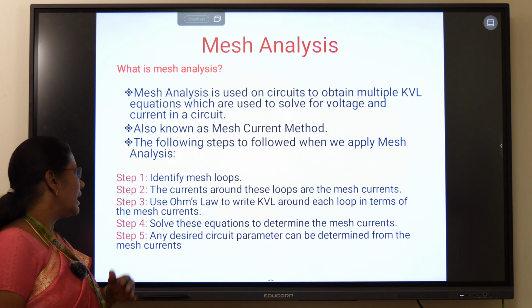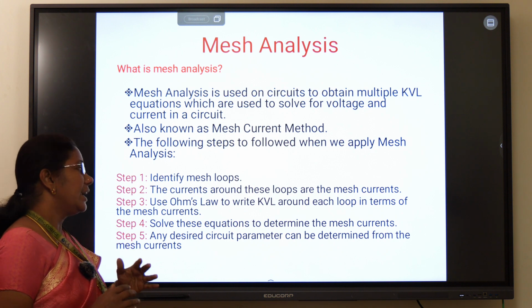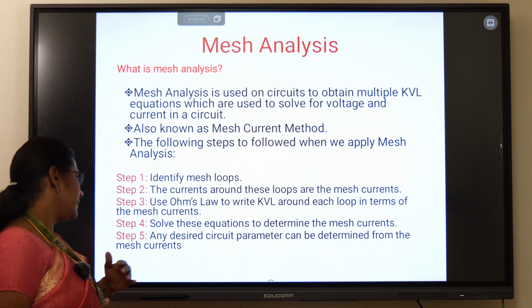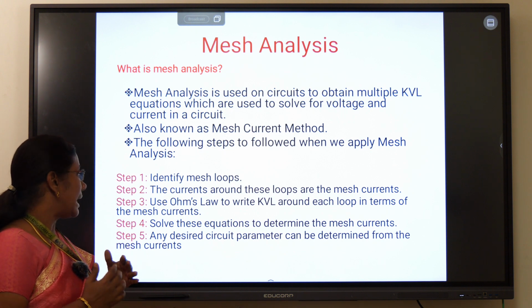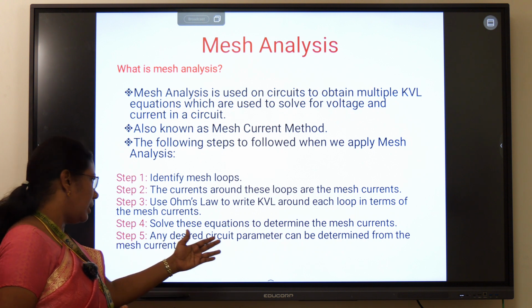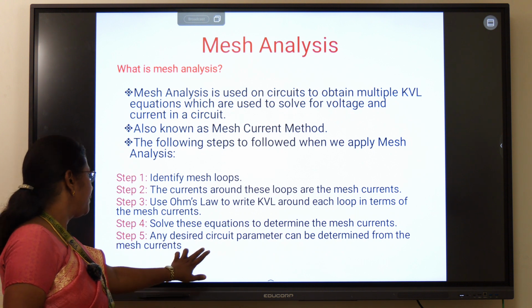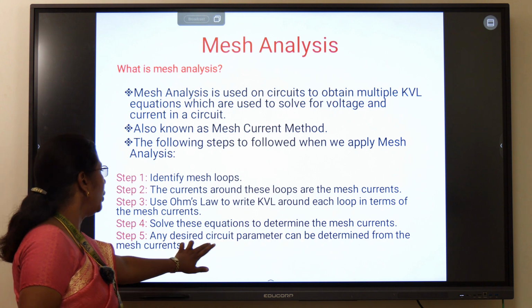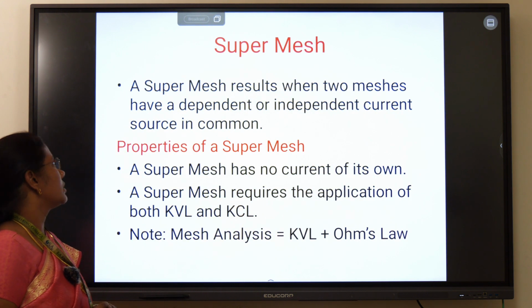Then in step 4 we have to solve these equations in order to determine the mesh currents. Then in step 5 we can find any desired circuit parameter from these mesh currents. So these are the steps to be followed in mesh analysis.